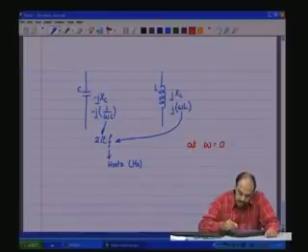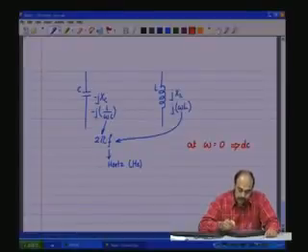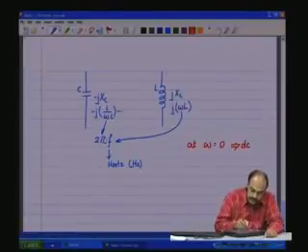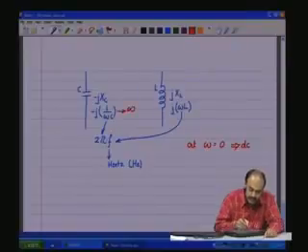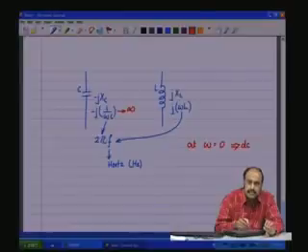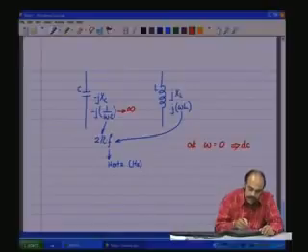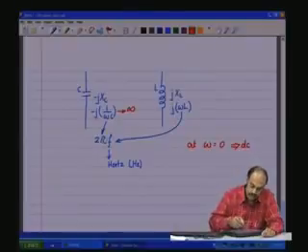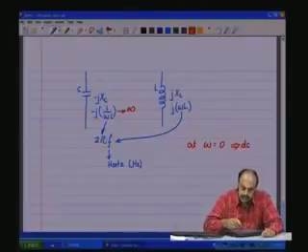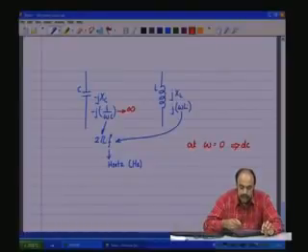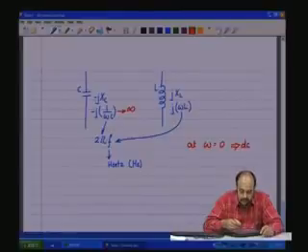It means the signals are DC. At omega equal to 0, this tends to infinity because omega is in the denominator, which means the capacitance provides very high, infinite reactance, which is the reason why the capacitance blocks DC. In the case of the inductance, at omega equal to 0, there is no inductive reactance; it appears as a short. At DC, it does not provide any impedance.